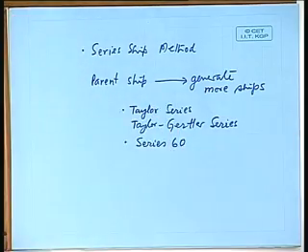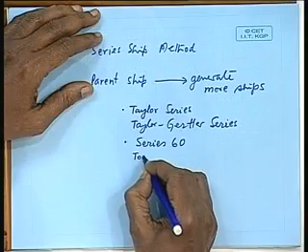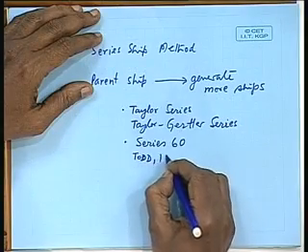A number of models were manufactured and tested, and we got a huge amount of data on series 60, not only on resistance. These vessels have been tested for sea keeping, for resistance in waves and maneuvering. So, large tests have been conducted on series 60 vessels, and a storehouse of data is available in open literature. The resistance data was published by Todd in 1963 in SNAME.